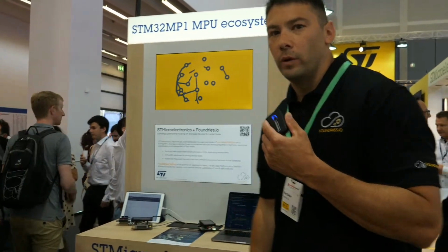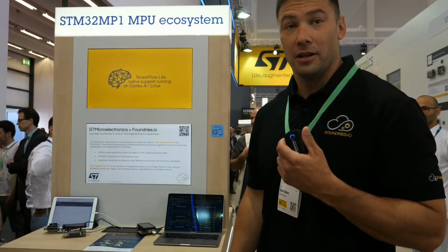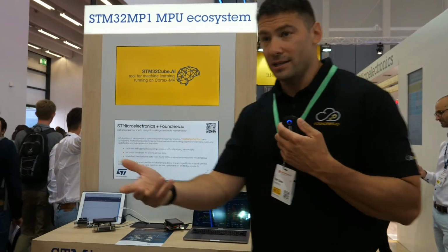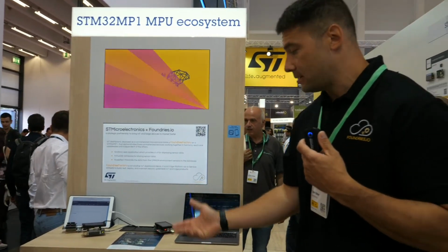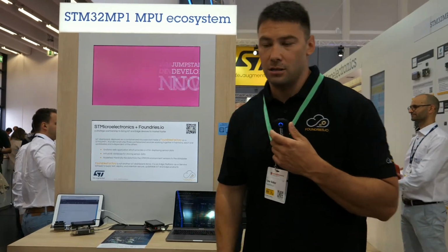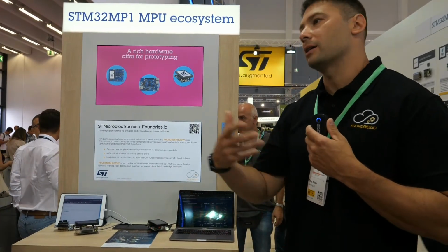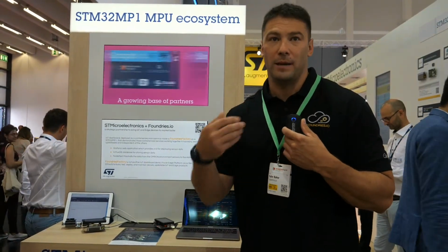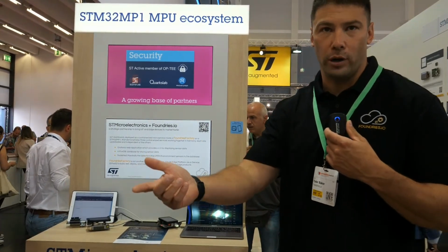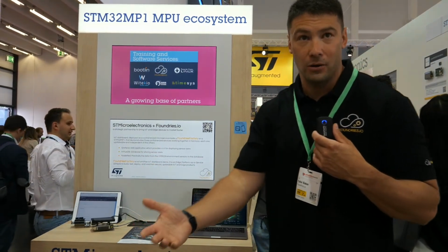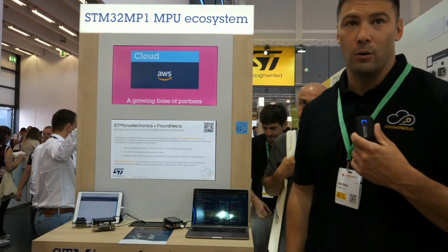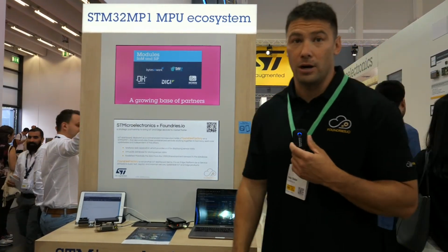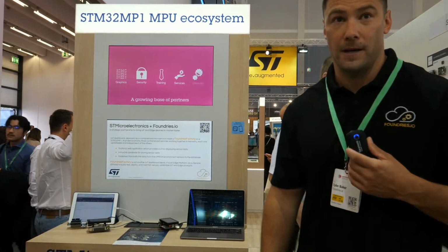So with our system, we can update every piece of software that exists on the device. That includes the microcontroller firmware. So a lot of our customers will build RTOS applications for their M4 coprocessor, and we can deliver it with our secure over-the-air system to the file system. And then a lot of our customers, depending on what they've added onto their design, have tooling to basically put the M4 into a DFU mode, which is like a firmware update mode, and then they're able to update the firmware with the payload that we brought down on the platform. So the answer is yes, we support coprocessor firmware and we support coprocessor firmware update.